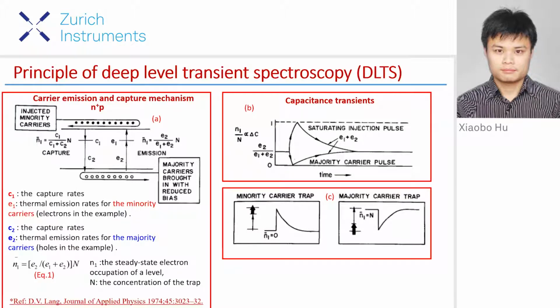We define an electron trap as one which tends to be empty of electrons and thus capable of capturing them. Likewise, a hole trap is one which tends to be full of electrons and thus capable of having a trapped electron recombine with a hole or capture a hole.